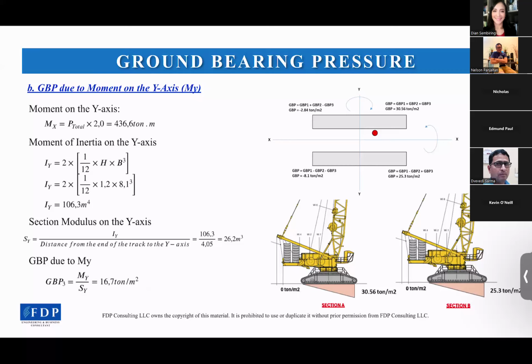Crane bearing pad specification depends on load capacity, and like Nelson said, material requirement, pad thickness, pad area or surface size, and also your soil condition. So I think there is no exact size for your crane bearing pad.